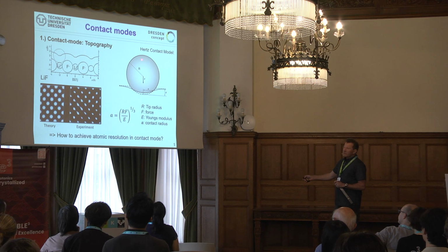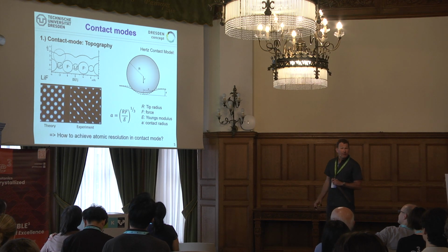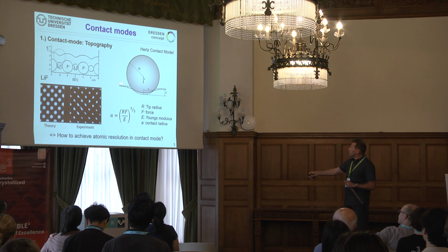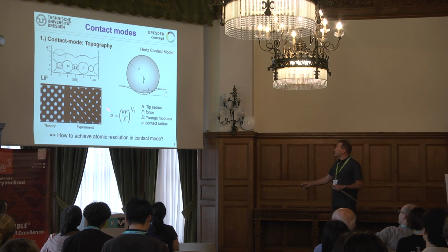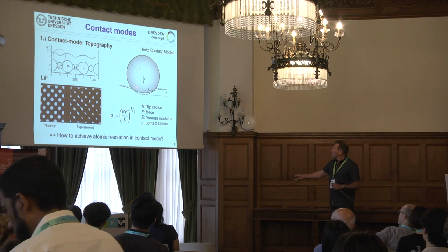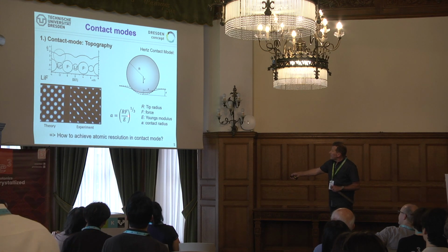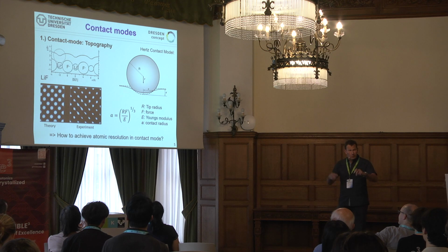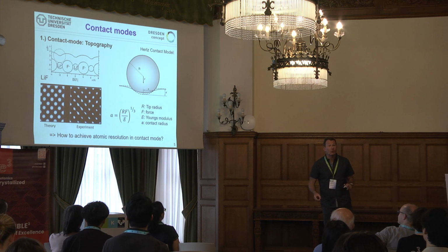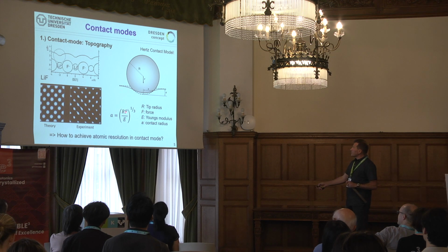resolution. And this is really described for the contact mode in the Hertz model, where we have, let's say, my tip with a radius r of 5 nanometers. We go onto the surface, we slightly compress into the surface, and hence we have a certain coupled E, Young's modulus, between the tip. The tip can deform, as you nicely see here, but also the surface can deform. So what you do basically is a series junction of E moduli, and then you can calculate what is the effective E. F is the force you apply, 10 nanonewton we said.